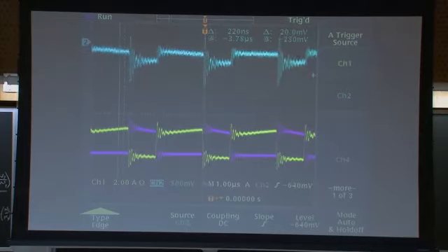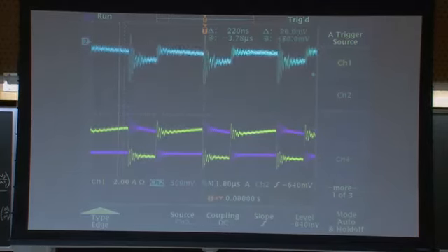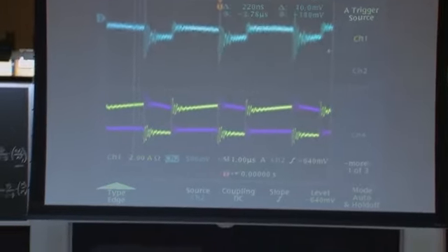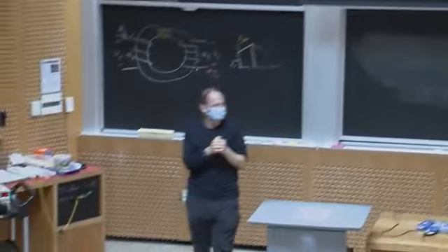So I'm storing the same energy in the core. The energy stored in the gap is actually continuous, ramping up and ramping down, but it's reflected based on different input and output currents. And that's because I can use a turns ratio, in this case a 2-to-1 turns ratio, to do that. So we can get this nice scaling and think of this energy storage transformer as an inductor plus an ideal transformer. Questions?